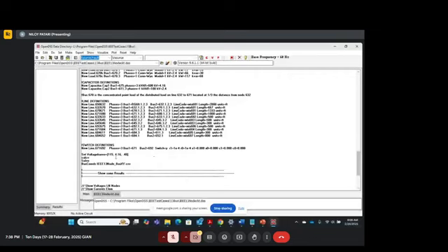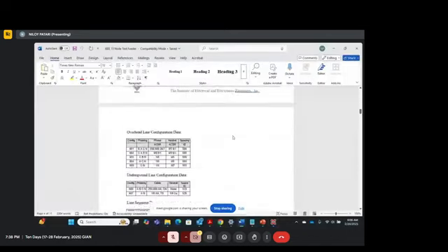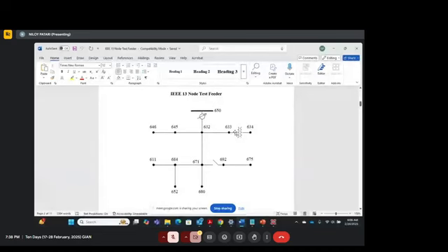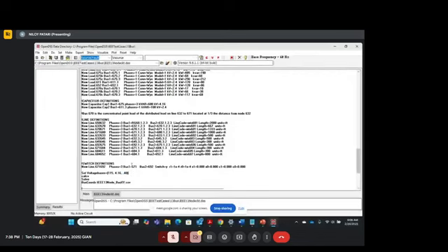You remember that in the substation you have this 115 kV on the primary side. On the secondary side you have 4.16 kV. And just after the transformer, if you see this transformer, which is between 633 and 634, on the 634 side you will have a very low voltage, which is 480 volts, which is 0.48 kV.